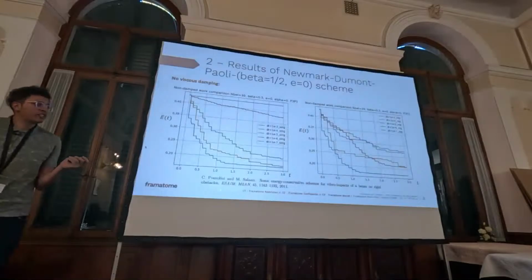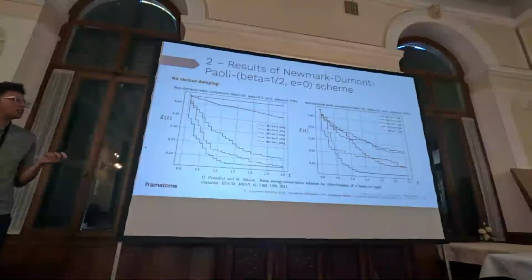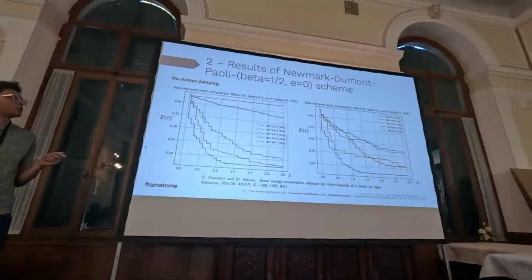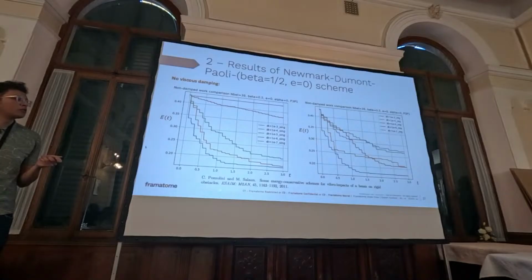In here, that's a state-of-the-art result, a comparison between singular mass matrix and the regular mass matrix. When we converge the time step, we get the accurate theoretical result, which is a constant energy balance and no dissipation related to contact, as opposed to the regular mass matrix, where we don't have a clear pattern that converges.